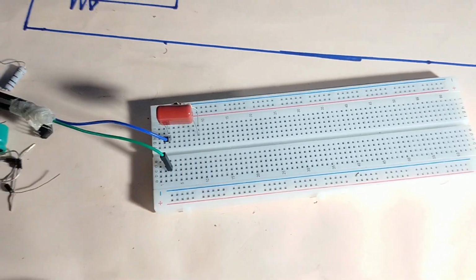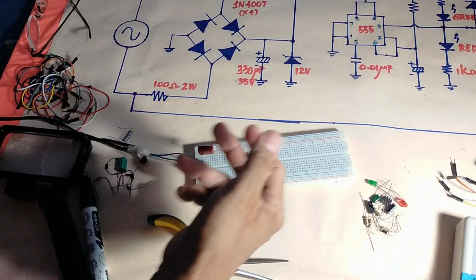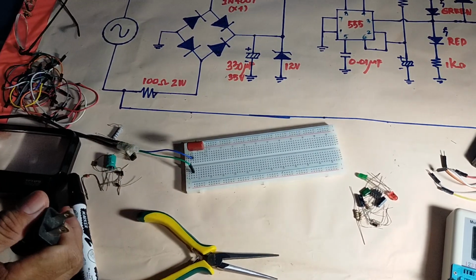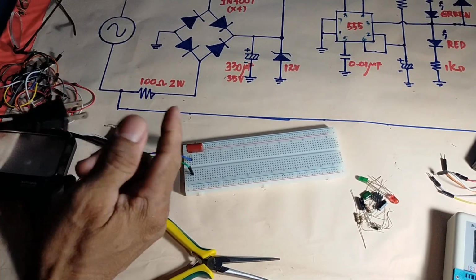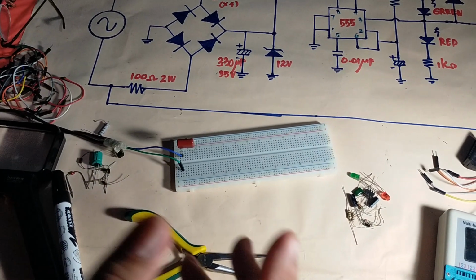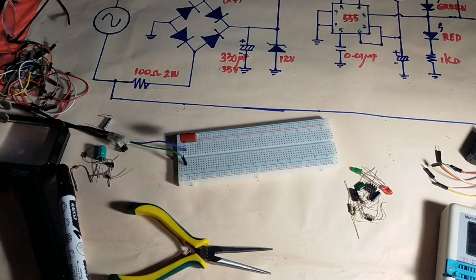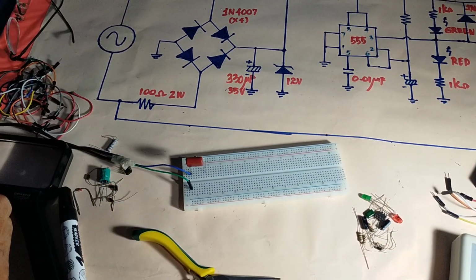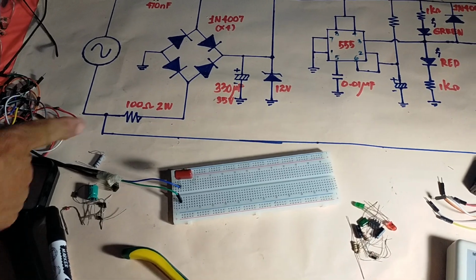Although the AC cord is no longer connected to the outlet, there is still remaining voltage at this capacitor if there is no resistor here. But with the resistor, the stored voltage will be automatically discharged to make us safe from the circuit, because if you happen to touch the terminals here, you can be electrified without the resistor.